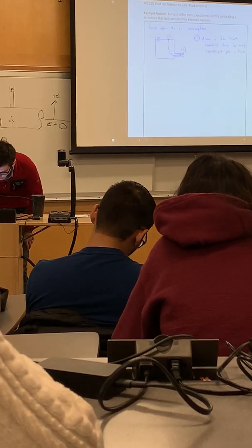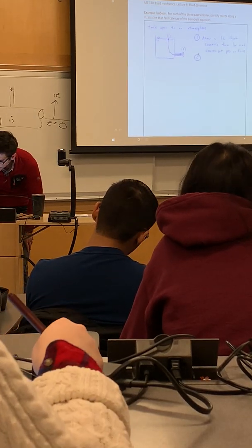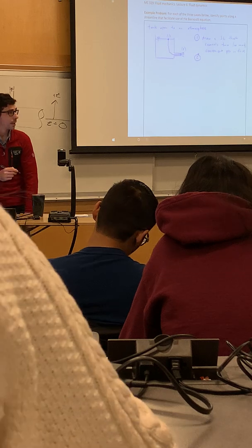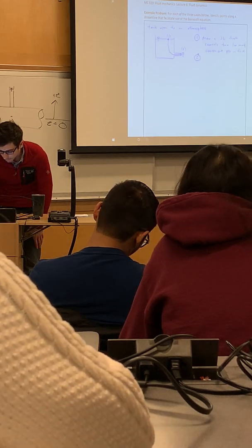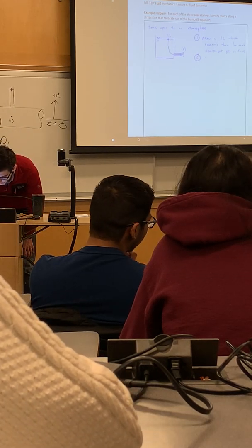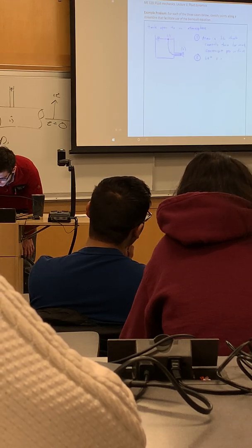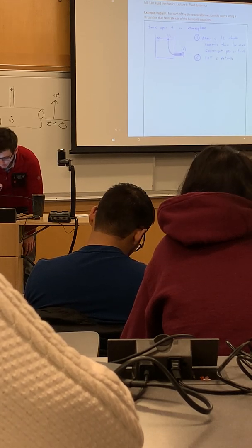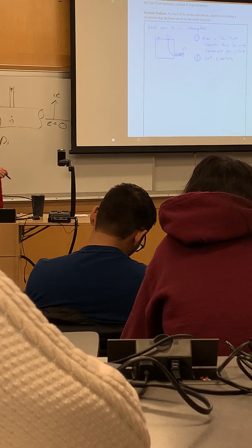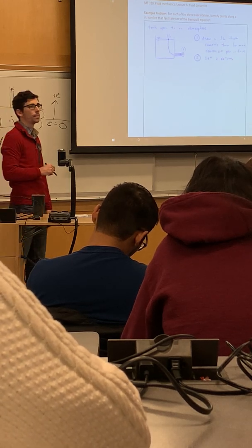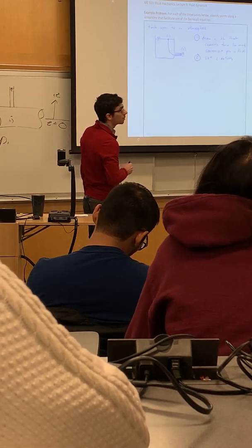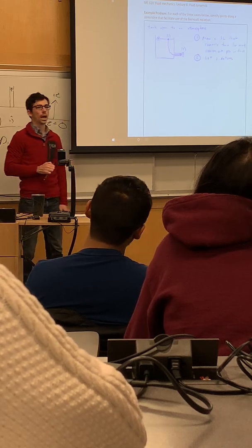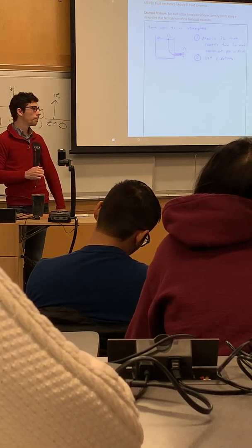So the second step that I'd recommend with these problems is to set your z-axis direction. And well, maybe even before that, set your z-datum. Okay. I see a lot of students in this class who are tempted to set the datum at the top of the fluid. And I really recommend not doing that.